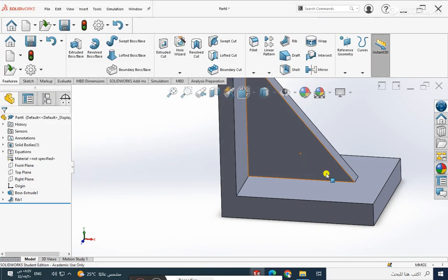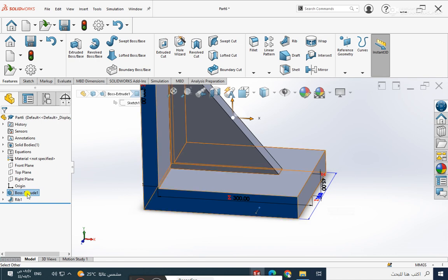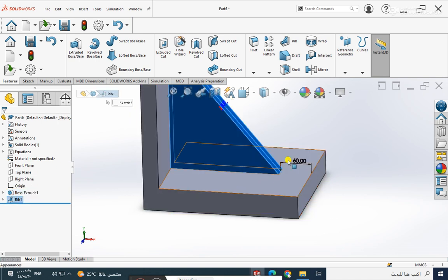The part is going to be bigger, and all the dimensions are going to be calculated. As you can see, this is 20% of 300. So you just have to change this L every time, and the program is going to change all the numbers related to this L, related to this global variable.